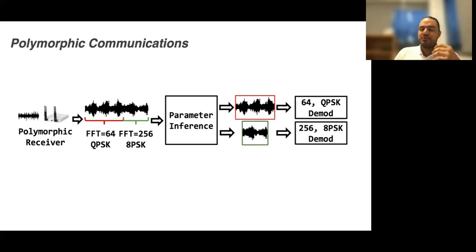to those transmitted signals without any prior knowledge. To give you an example, imagine that we're sending OFDM using QPSK in each sampling, and in a specific bandwidth. With a few IQ samples, we can infer that, and then adjust our receiver to receive that inferred signal in real time. In this way, we can have receivers that work without any prior knowledge from the transmitter.